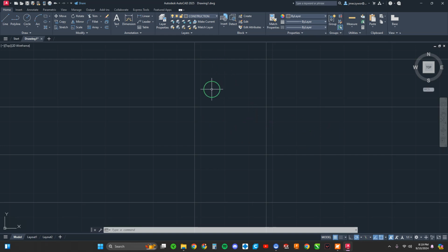So the next thing we're going to do is we're going to go ahead and create the outline of our views, all right? So we're going to come up top here. We're going to put our object layer on, and then we're going to type L this time, not XL, just L for line. Hit enter, hover over the corner, click, click, click, click, click.